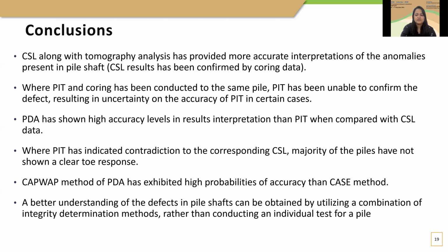The majority of the piles which have shown opposite results to CSL have not indicated the clear toe response, which could be the reason for the variations in the test results. And when considering the PDA data, the CAPWAP method has shown higher accuracy levels than the case method.